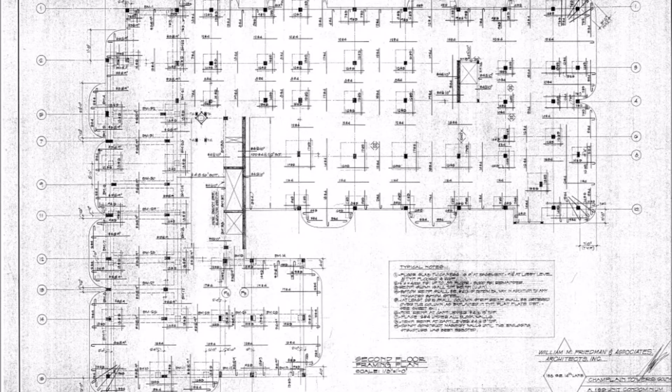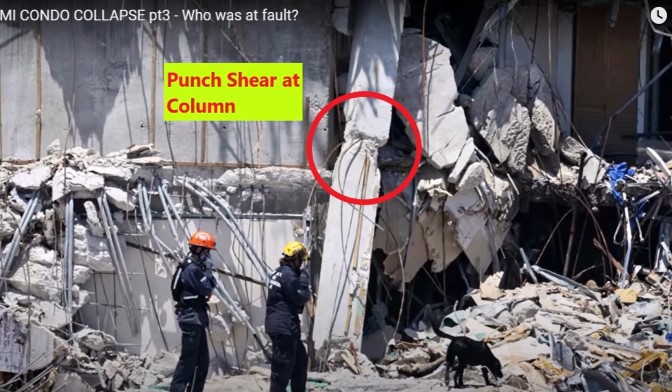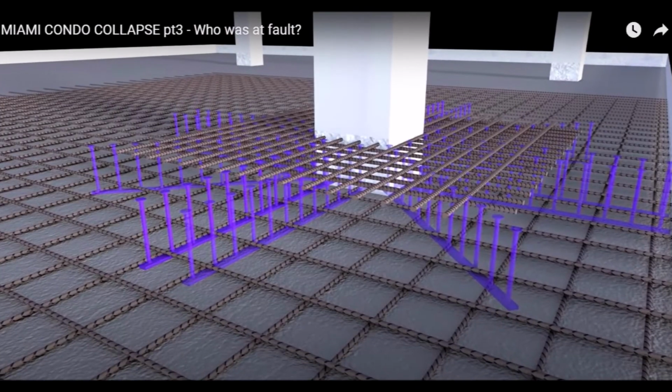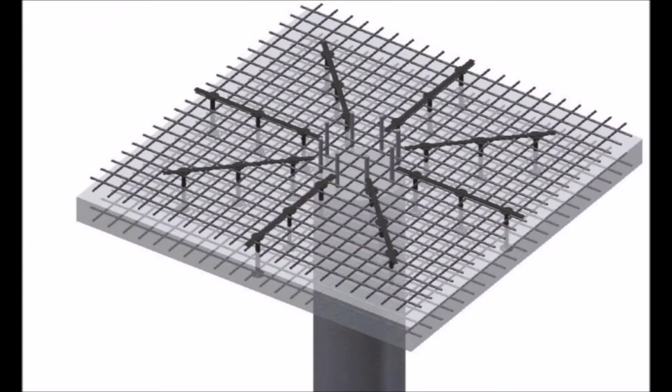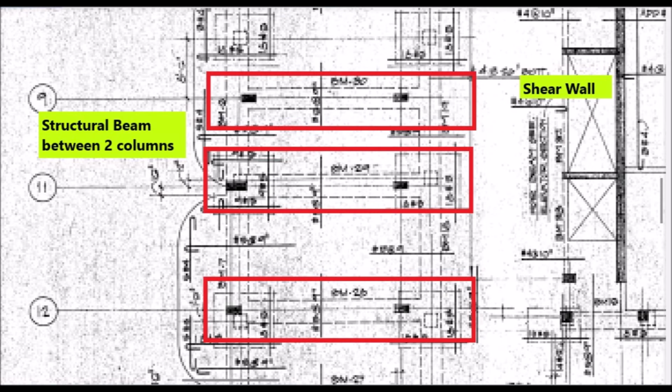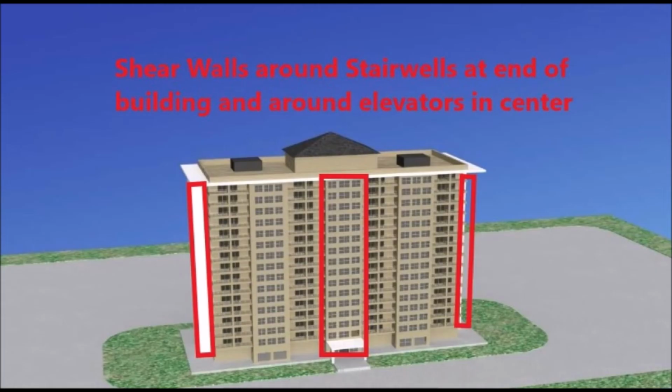There is also a discussion among structural engineers of the lack of punching shear reinforcing steel at the column locations. Some structural engineers now suggest that the punching shear rebar would have strengthened the columns and would give some factor of safety in the building. Transfer beams would also increase the stability of the structure, as it did on the west side of the building, and then possibly adding another bank of elevators on the east side and encircling it with a shear wall from the ground level to the penthouse floor.